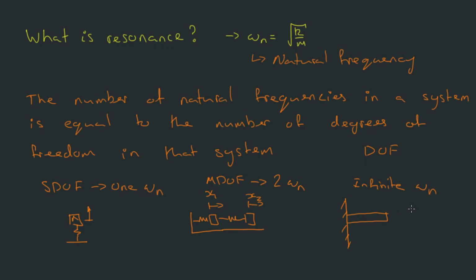Now, the natural frequencies are predominantly most disruptive at the lower frequencies because the amplitudes are much higher, and that's often where we tend to see them. So it's just important that we know where they are and we can work around it. So basically that's natural frequencies. We want to be able to calculate them and avoid them.